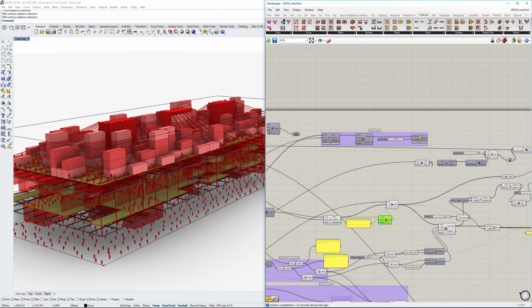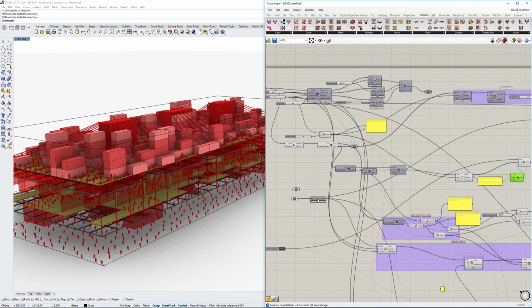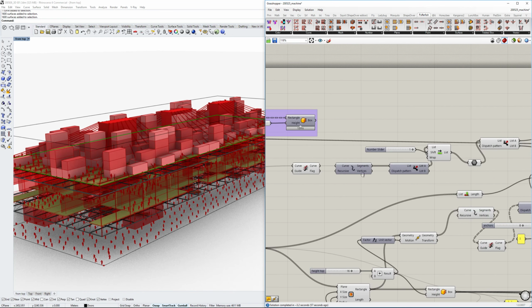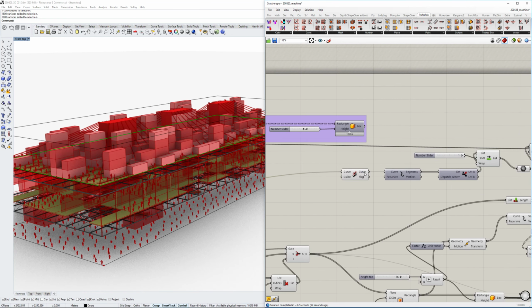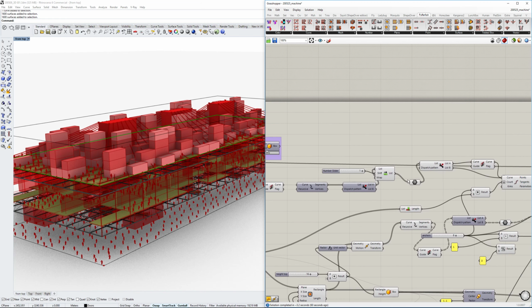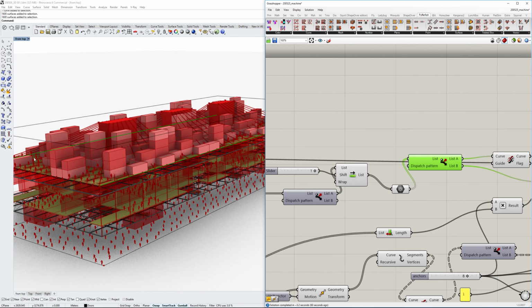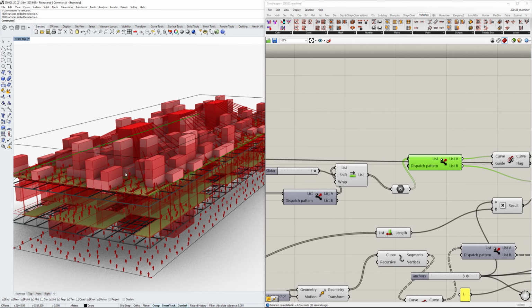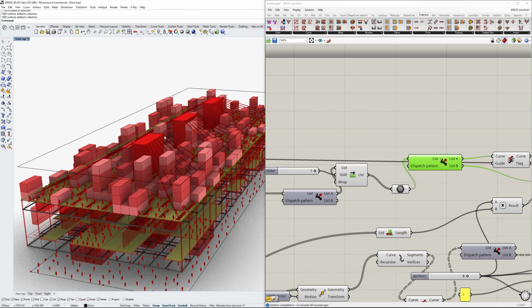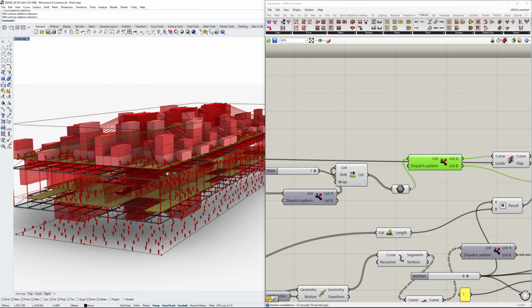Actually, when we're here, we can continue with this. We have another surface as well, a very simple one, this rectangle surface as we had it in the beginning, and we want to check the surface and take the one piece from the other piece, because we want to create a pipe pattern that goes from the top of our structural concrete component to the end of our steel construction, which would be here in the middle.